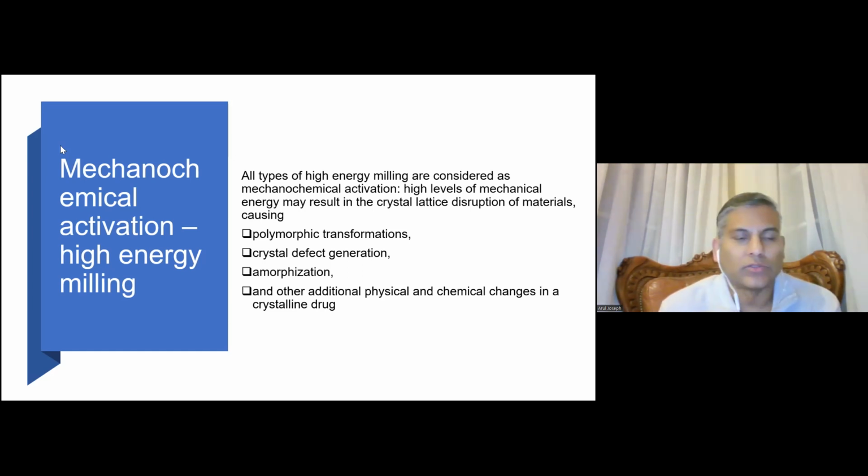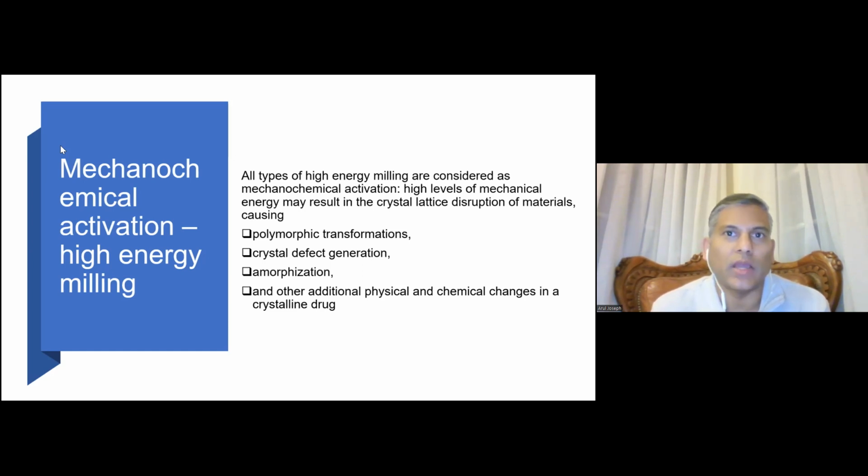a crystalline drug. So sometimes the issue with milling can be that if you have a particular polymorph, you want to keep it that polymorph. When you use high energy milling, there is the possibility that polymorphic transformations happen, and that can lead to lower solubility and lower bioavailability, right?